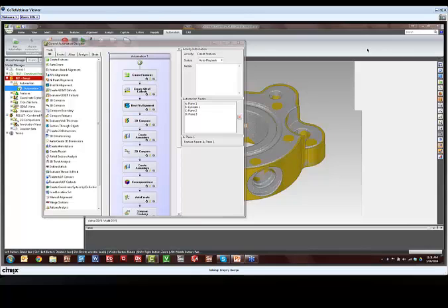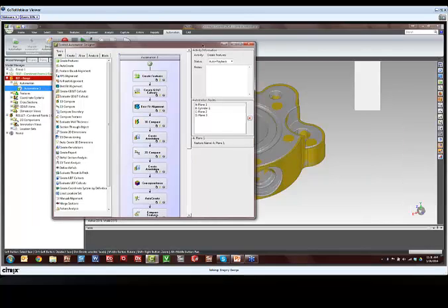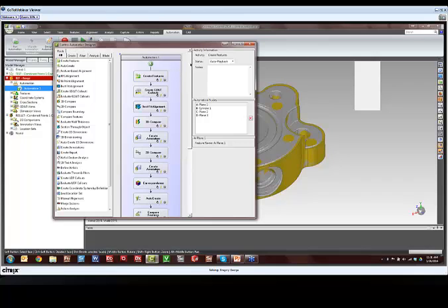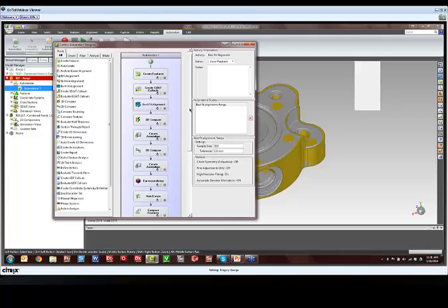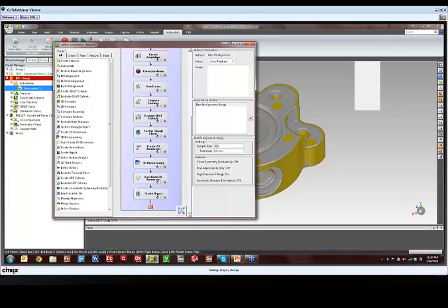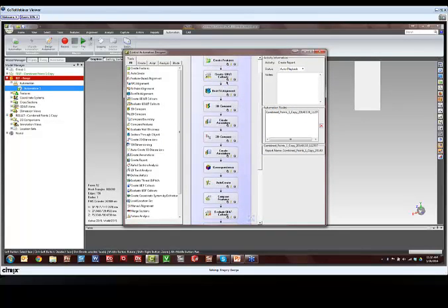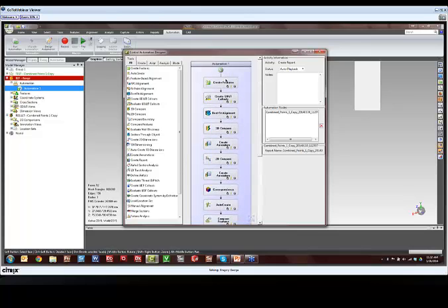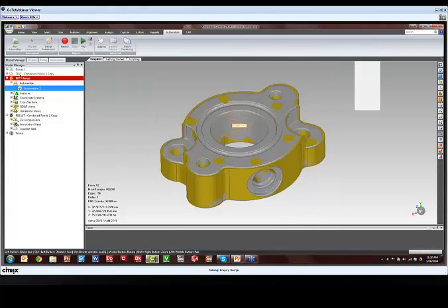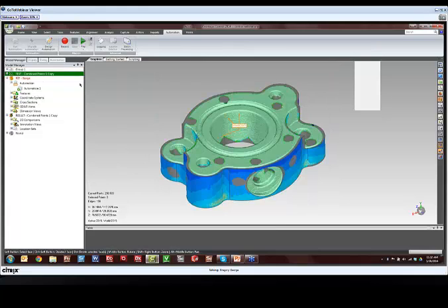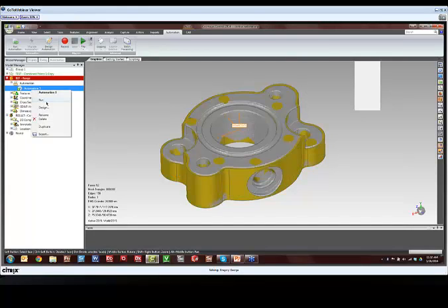All right, so now that you can see my screen again, this is the automation tool that I referenced. Everything that we did, where we created features, did a best fit alignment, 3D comparison, all the way down through creating a report, is all recorded here with all of our settings. And it learned that as I created those measurements. So all I have to do if I want to run this inspection again is scan another part, come over to this automation tool, just right-click on it, and then hit run, and it'll run that same exact routine on the next part.